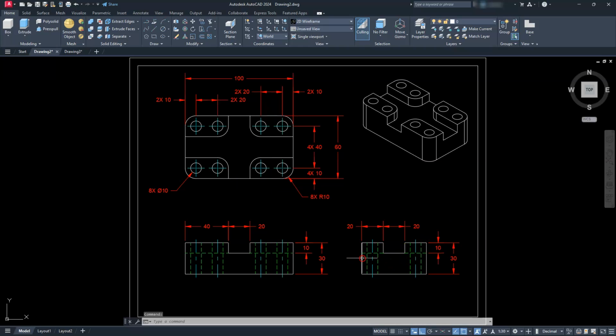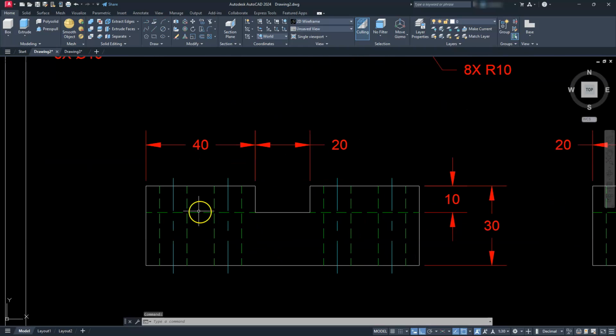So what's happening is that I'm located at this dotted line here. So that's where I'm at. What I want to do is extrude from this point down, so you can see that I have a distance of 30. If I subtract the 10 from it, that's going to leave me that this distance from here to here has to be 20. So that's what I'm going to do. I'm going to extrude this block down to a height of 20. All right.